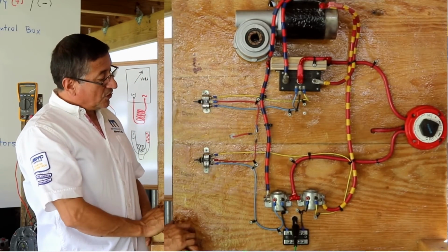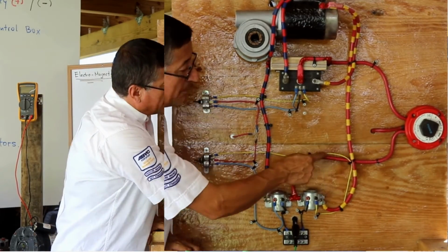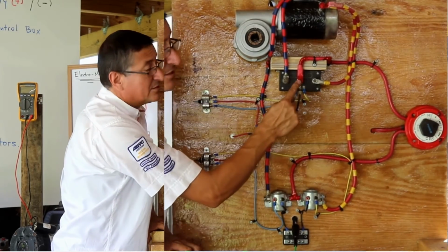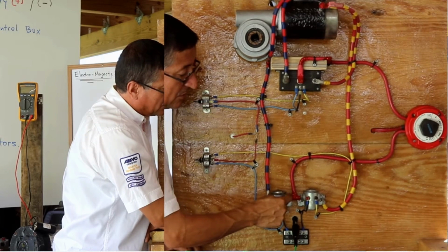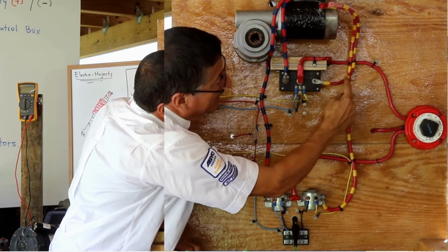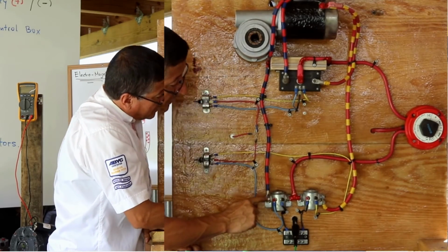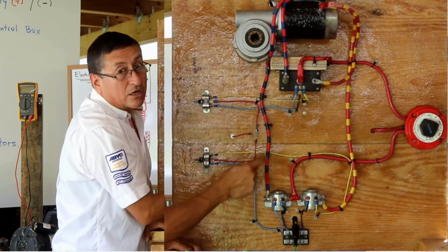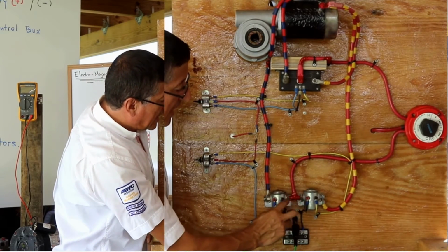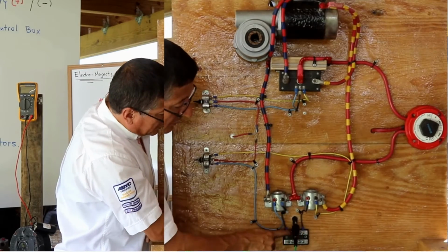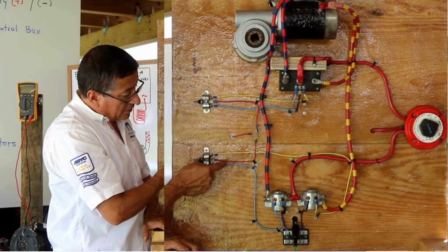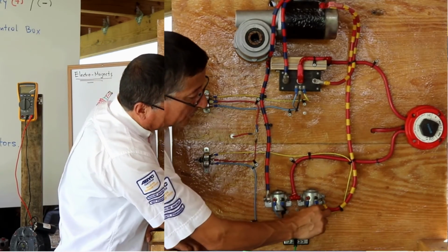And this is the procedure to connect the relays. I enter with the power coming from the battery in the middle, exactly the same as this. The power enters in the middle. And the output of this relay goes for clockwise rotation, and the output of this relay goes for counterclockwise rotation. The middle terminals of the relays should be connected to the ground bus bar, and the externals, one for clockwise and the other one for counterclockwise.